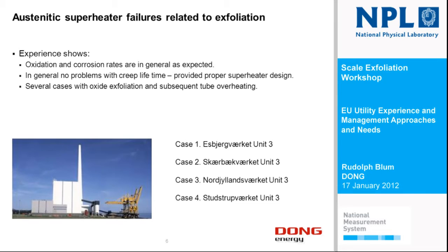What I'm going to tell now is a failure which occurred in the SBR unit and the two ultra supercritical units, and which could have occurred in this unit. This is just a plain supercritical unit, only operating at 540. But it has a lot of austenitic materials in the superheater because of a very bad superheater construction, which led from the very beginning, after only 1 year of operation, to an extensive replacement of good X20 material with austenitic material to overcome intensive overheating.